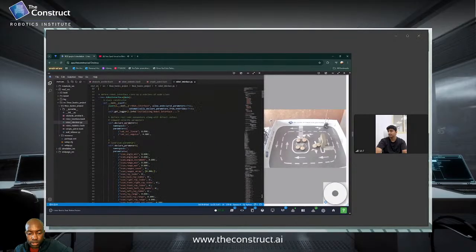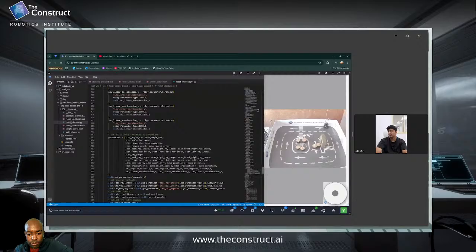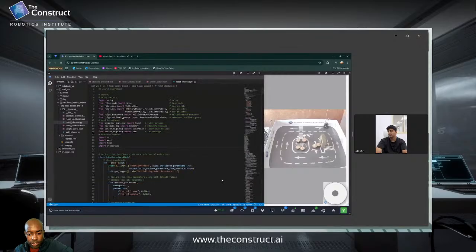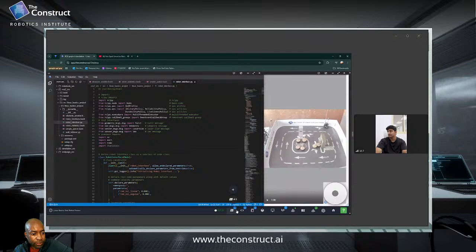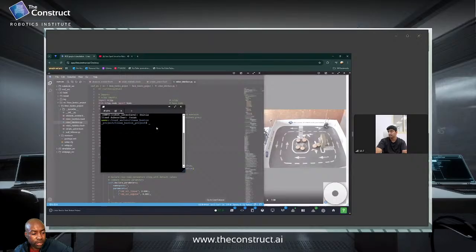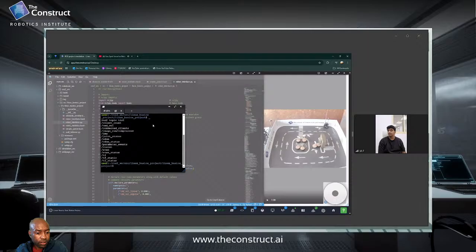Oh, you didn't start the simulation. You have to start the simulation first. But you're connected to the real robot, so it's supposed to work there. So okay, what's going on? Can you go to the terminal and do ros2 topic list to just see what topics we've got? ros2 topic list. Okay, so we've got all those ones being published. That's fine. So we're connected.